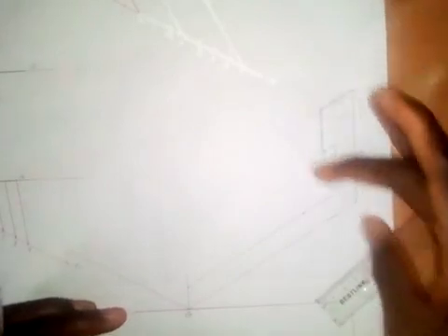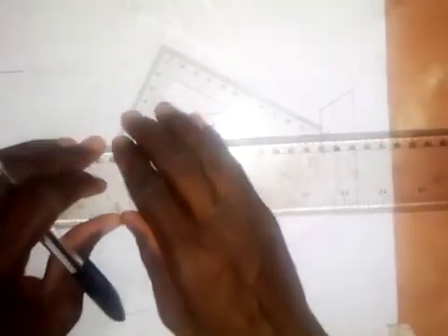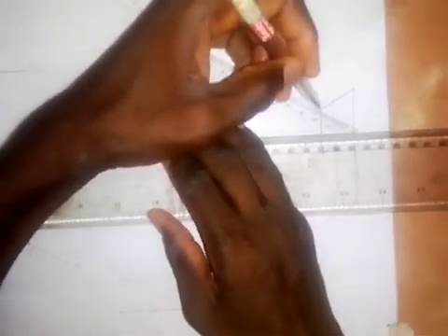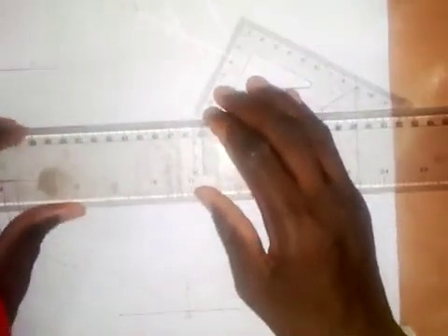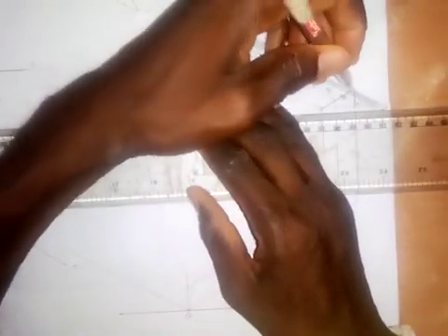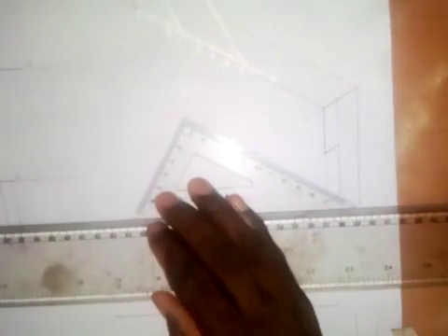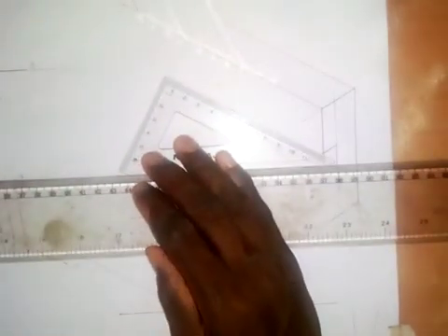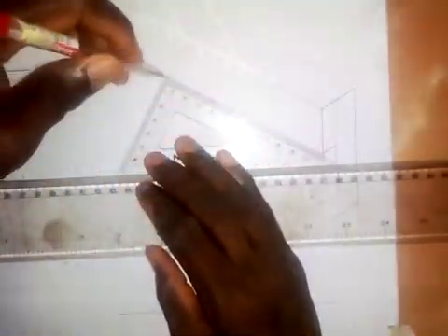The next thing I'm going to do is that every point we have on this object, we have to transfer to the other side. Just look at the way I'm going to do it. I'm going to start from here. You set your set square here and transfer this point to the other side, and here also, you transfer this. Coming here also, I will transfer this to the other side,